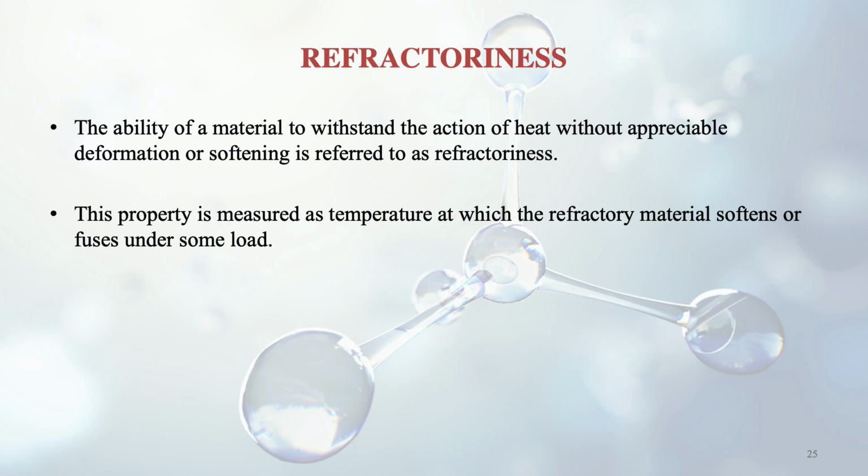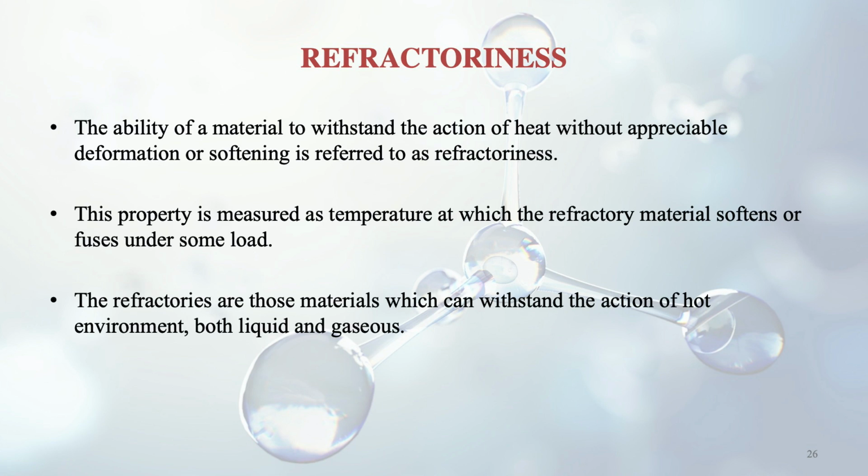This property is measured as the temperature at which the refractory material softens or fuses under some load. As soon as we reach a temperature where the material is softened or fused, we can know the capacity of that refractory material. Refractories are those materials which can withstand the action of a hot environment, whether liquid or gaseous.